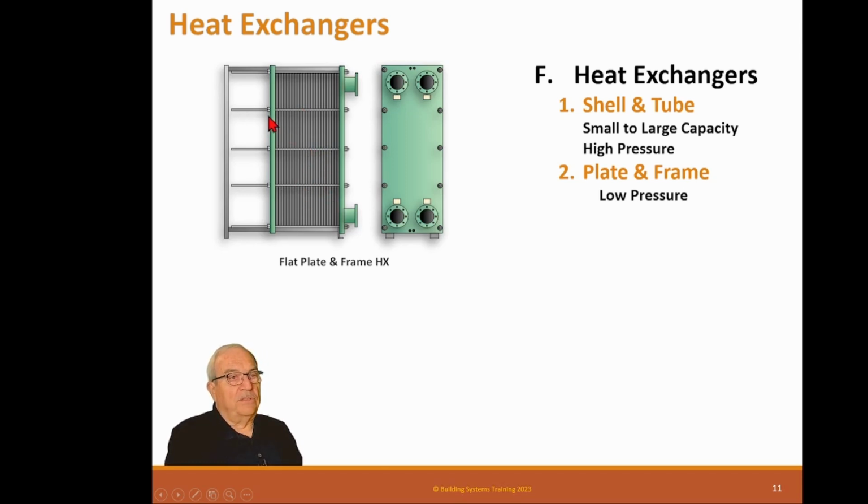So what you do is unscrew these bolts and pull this back plate off, and then these plates can come loose. You can take them off and wash them and put them back. However, these plates are not like the old milk plates. Their gaskets aren't really made to be taken apart every day. You can take them apart to clean them, but it's a job. I've had guys work on these. It takes two guys an entire day to just put one back together.